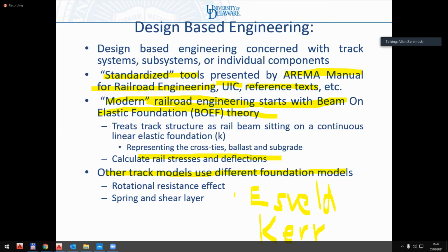for analyses. For example, when I was doing the work on the East Line of Israel Railways, I used beam and elastic foundation to develop the load distribution that was going ultimately into the ballast and into the sub-ballast to determine what support conditions I need underneath and what type of additional design features I need to add to reduce the stress levels.